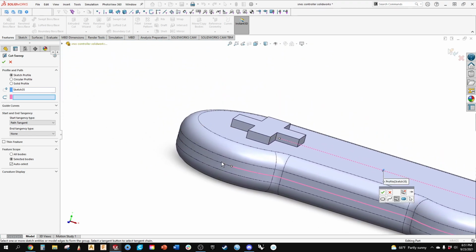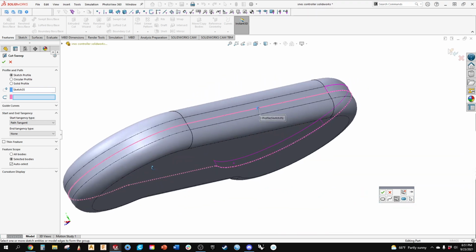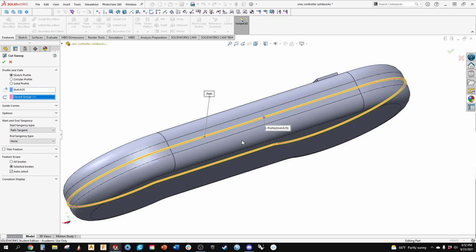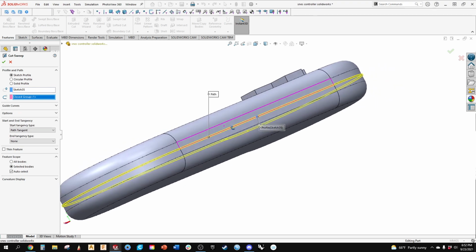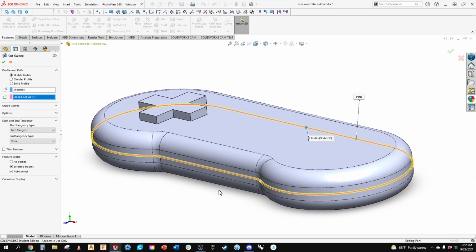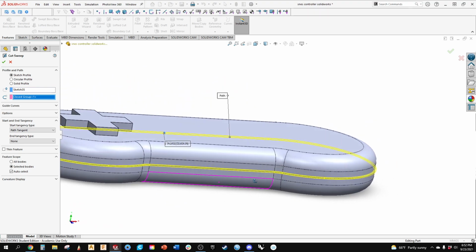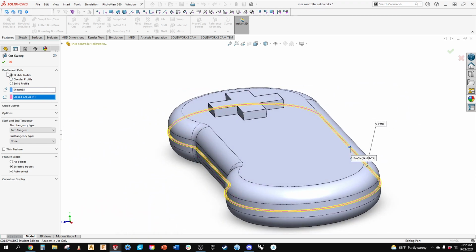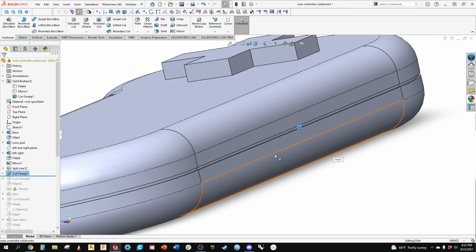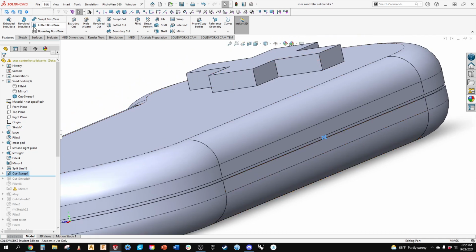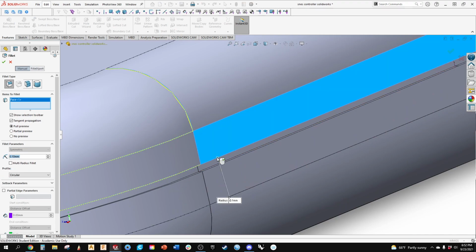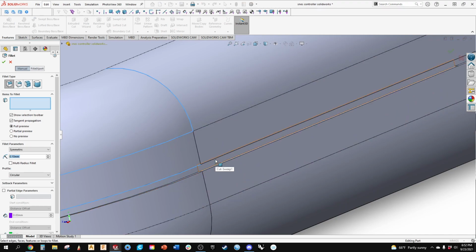And there's multiple ways of doing this. We could have actually split the part into two and then done offsets. So here you see that it's going all the way around. Again, when you do a command, build and evaluate, so it looks like it's good. So now we've kind of got our fake part line in there. We can dump some quick little radiuses on it. Oh, not the face, but the edge.